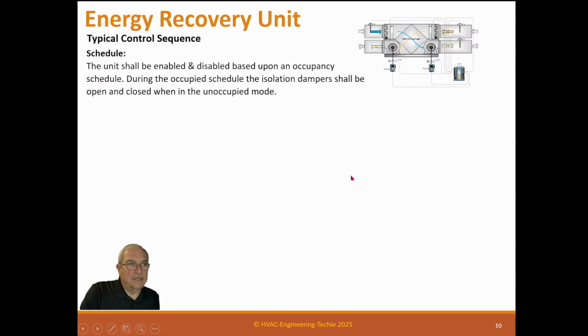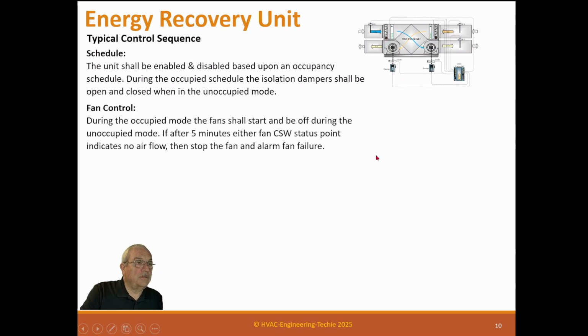That's what it does. So it's scheduled. The unit should be enabled or disabled based upon an occupancy schedule. During the occupied schedule, the isolation damper shall be open and closed when in the unoccupied mode. Again, we need it to be sealed when the building is not occupied. During the occupied mode, the fans will start and be off during the unoccupied mode.